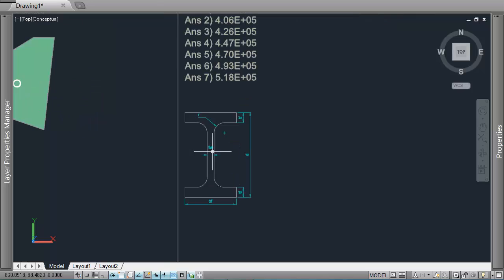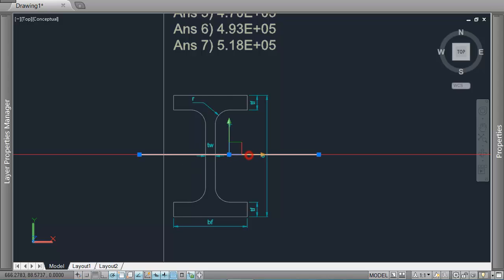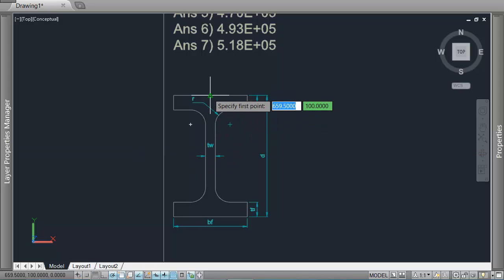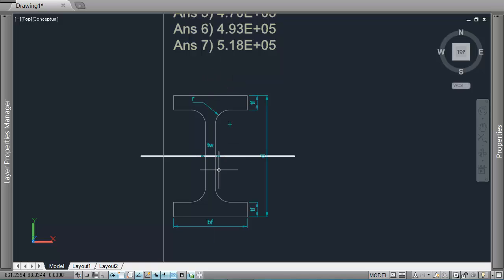So an I-beam could be bending about this line, so bending top to bottom, or it could be considered to be bending left to right. But because there is much more material in the cross-section separated from the neutral axis in the above and below case, this is referred to as the strong axis of the beam. So this other axis here we're not particularly worried about.